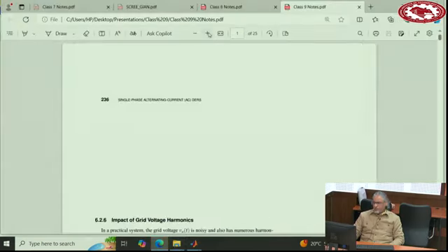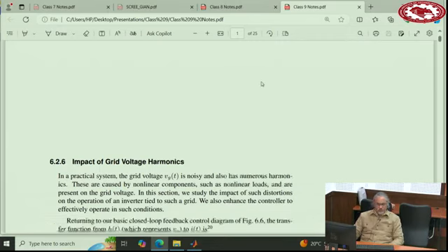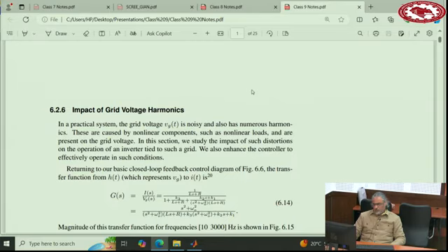All right. So we discussed the basic structure for the single phase AC grid connected inverter, if it wants to follow the commands of real power and reactive power. Now let's discuss a few issues around this topic. One issue is the grid voltage harmonics. Harmonics exist in any AC grid, especially harmonics 5, 7, 11, those harmonics, even some odd harmonics. They are there.